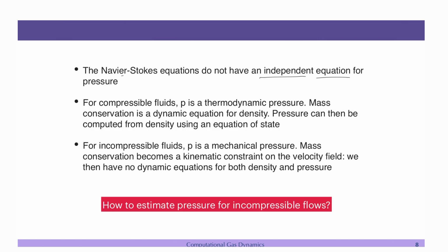But for compressible flow, the good thing is that P is a thermodynamic pressure, that means P equal to rho RT, right. So, if you know the temperature and the density, you can get the pressure. Okay. And you have the density from the d rho by dt, the first equation you have, and the temperature comes from the energy equation that you have. In fact, the energy equation can be written in many different forms. So, you can have an enthalpy equation, you can have the kinetic energy equation, you can have rho E plus P. This is enthalpy.